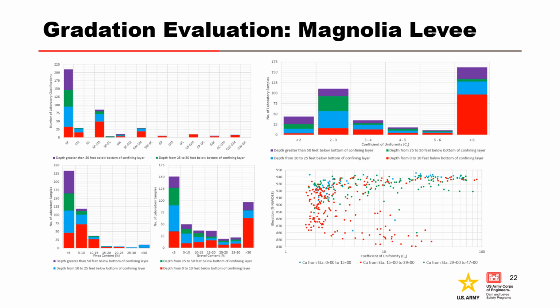This type of data presentation can be helpful in assessing the susceptibility to backward erosion piping. However, do not place too much emphasis on statistical evaluation without meshing the results with site characterization, geomorphology, and performance data. As previously discussed, discrete layers or channels can govern backward erosion piping, which may be missed in a boring and statistical evaluation.